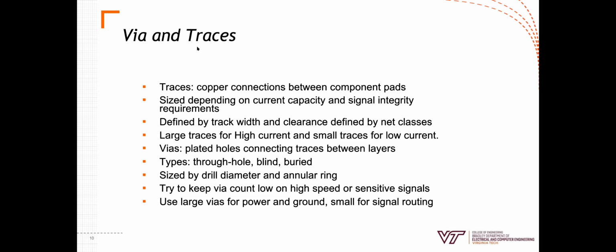So vias and traces. We've previously discussed this, the picture of the PCB, but these are just brief descriptions of what they are. Traces are copper connections between component pads. Their size depends on how much current you're pushing through them.